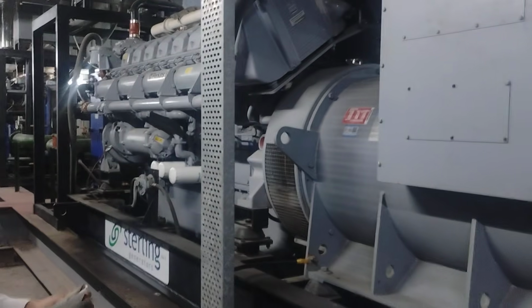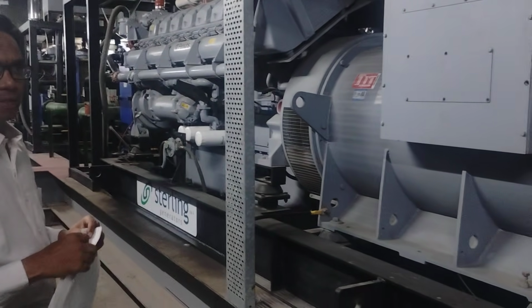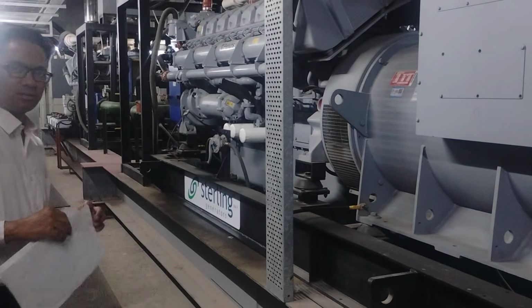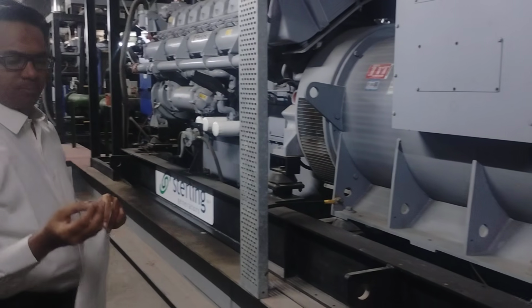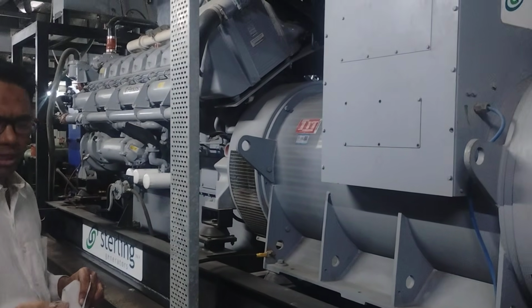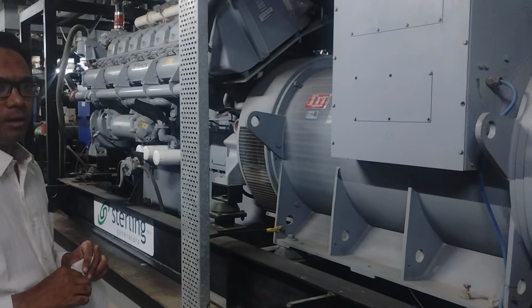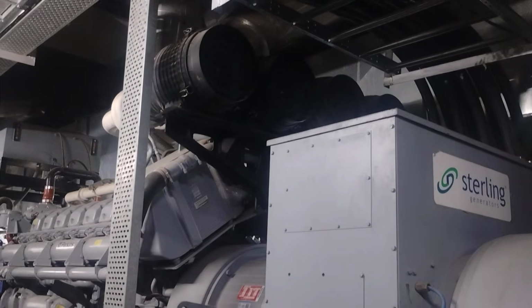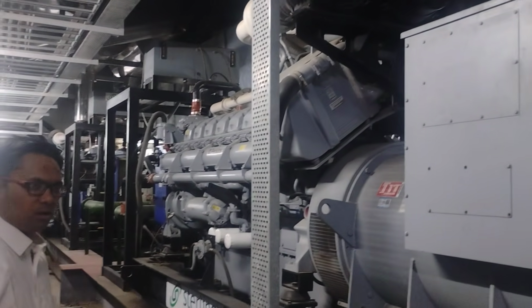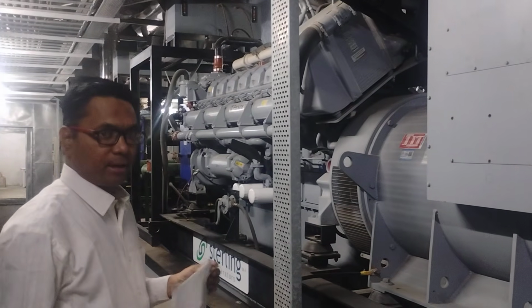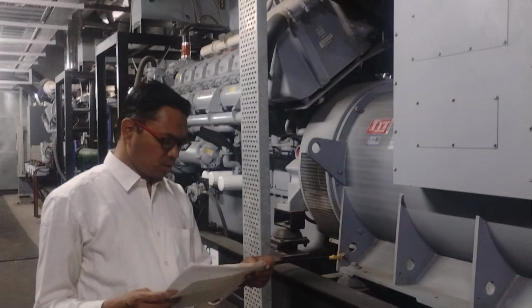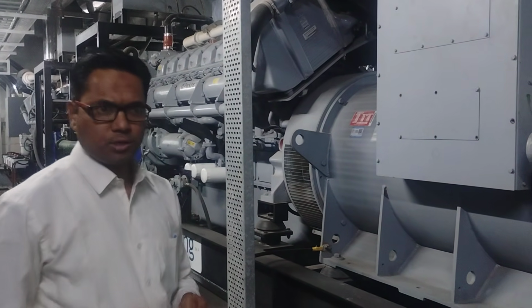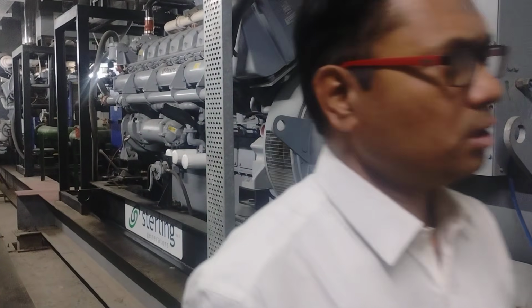This is the engine. Entire engine is there, and in that controller you can get the readings as well as controlling of the alternators and these parameters: voltage, current, kW, kVA, and frequency. And in engine section you can get the readings of the engine parameters like speed, oil temperature, oil pressure, battery voltage. So this is the brief and short explanation about the controller Deep Sea Electronics.